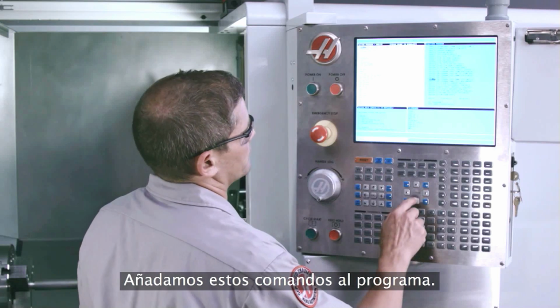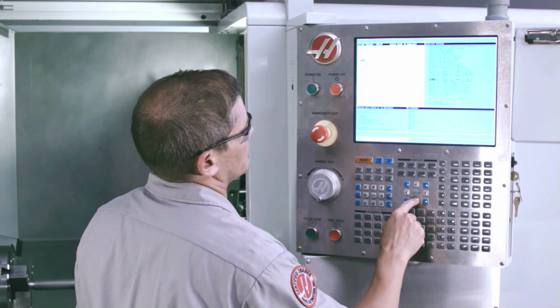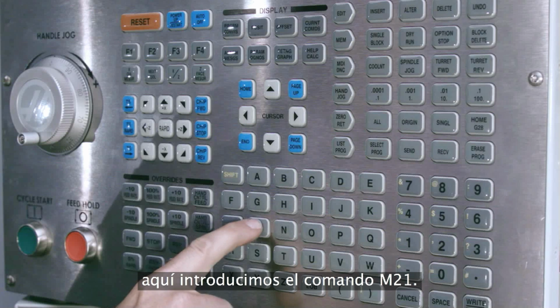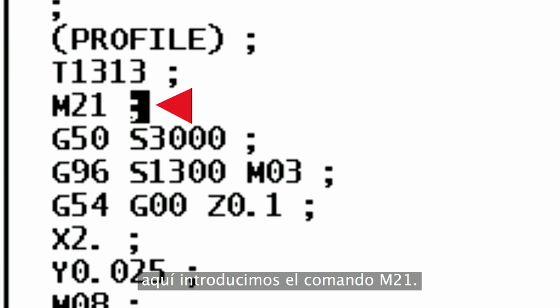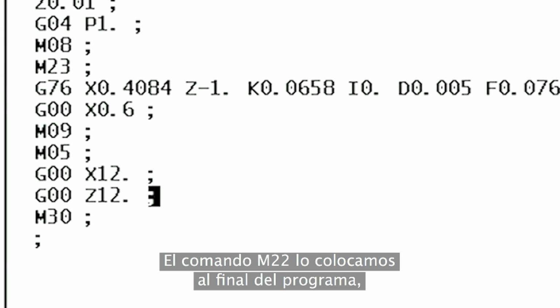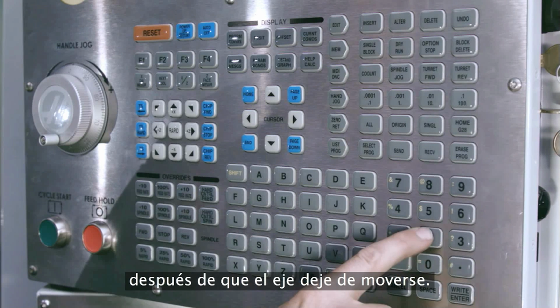M21 is the tailstock advance command, and M22 is the tailstock retract command. Let's add these commands to our program. We cursor down to right after the first tool is called, and this is where we insert the M21 command. And at the program's end, this is where we'll insert the M22 retract command after axis motion is complete.